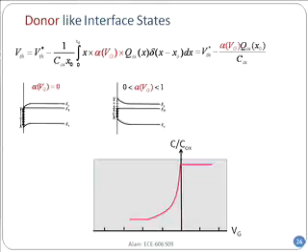Now let's say I'm beginning to go the other way, beginning to deplete, right? So I have to apply a negative bias because it's an N substrate. Now as I am beginning to deplete, a fraction of the defects have moved up above the Fermi level. Do you see that? Therefore, now I have some charge contribution which will change my threshold voltage.